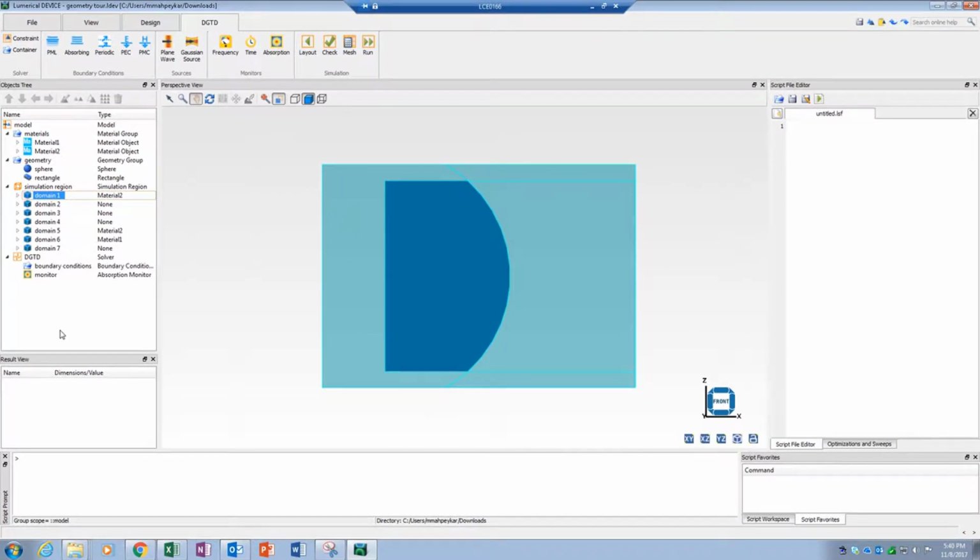In the event that both overlapping objects have the same order, the mesh order will be inferred from the objects tree. Objects at the bottom of the tree will take priority over objects at the top of the tree.